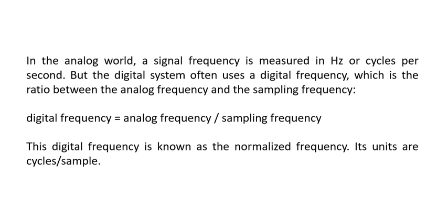In this concept, we'll discuss how we can design and generate this normalized frequency. Some signal generation VIs use an input frequency control F, and assume it is a normalized frequency with a unit of cycles per sample.